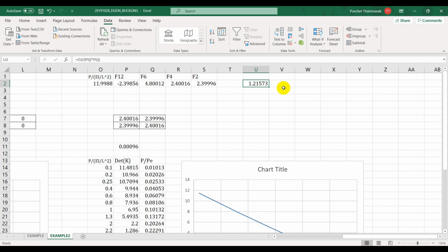Cantilever column moves the most at the top, and you have the degree of freedom set up at the top. So that picks up, that is very sensitive to the buckling. Whereas in this case, we have pin and pin. You pick up the rotation, but the two rotations at the top and bottom are not as accurate, not as sensitive as the middle column displacement. So it gives you higher buckling load, 20% more.